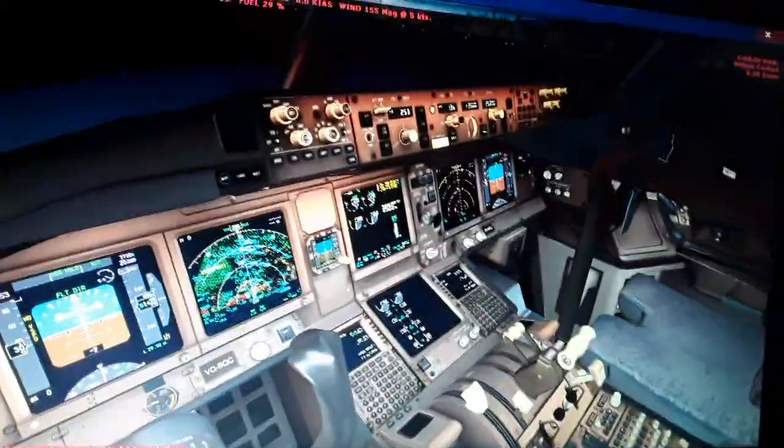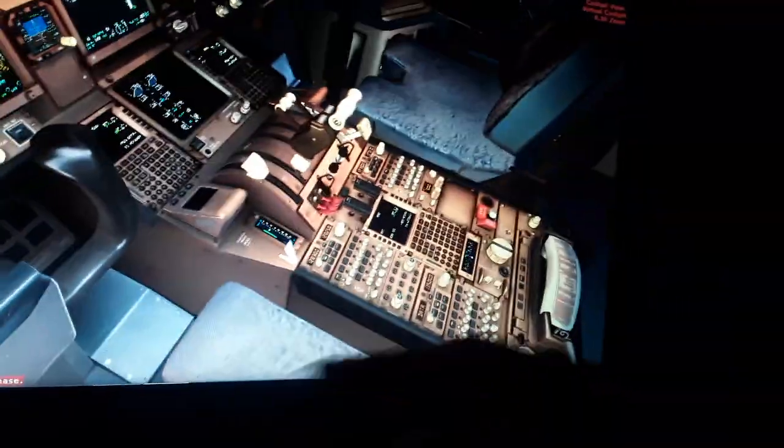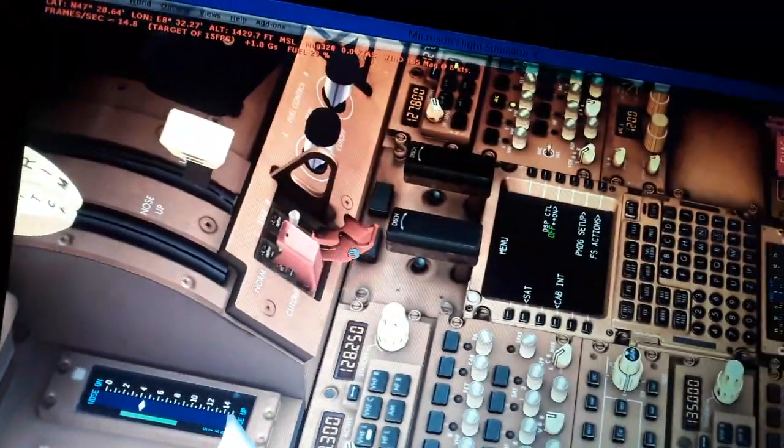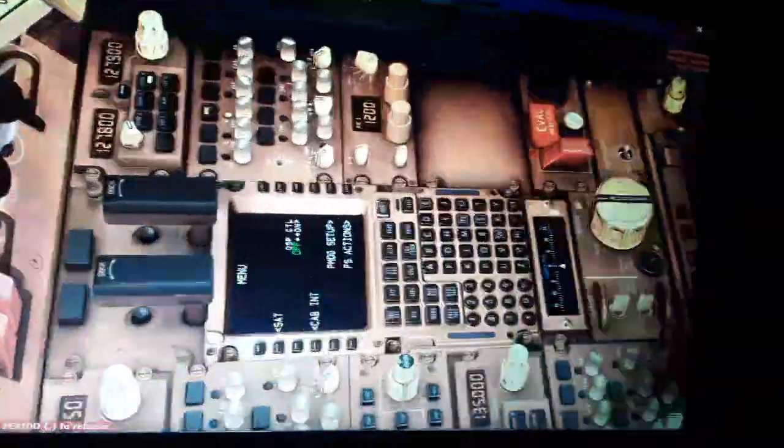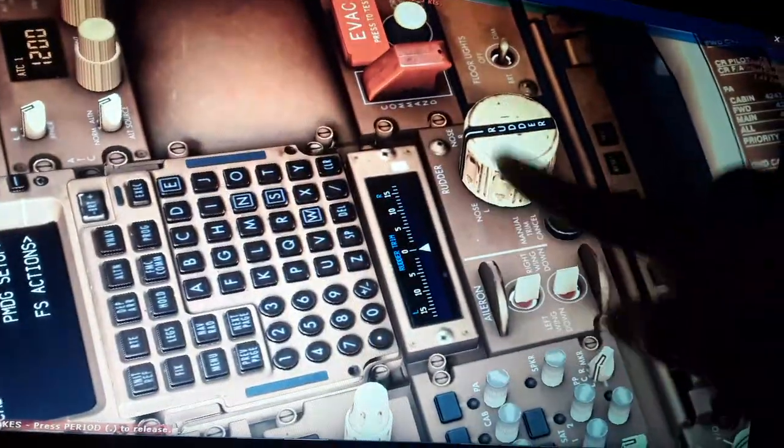Now we have to do the other things. So we use also the parking brakes. You can see up and down here, parking brakes up. Gates. We have also to close this guarded switch. We have the radio and communication panel. You can see we have also the vertical tail, the rudder trim. We don't use that often, and the aileron trim.